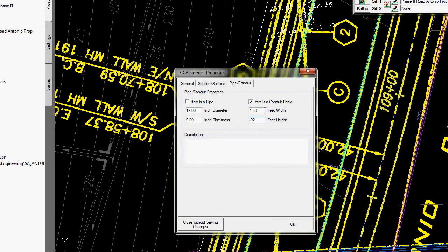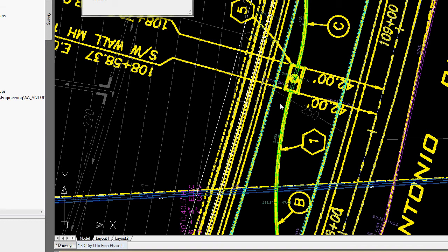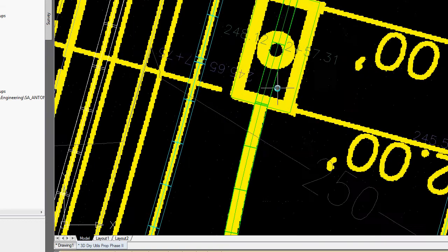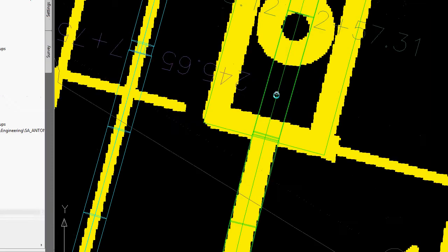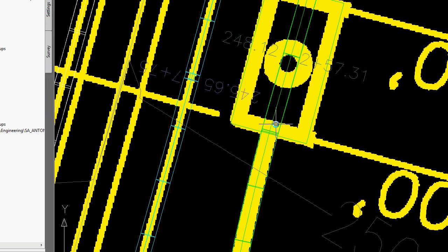Okay, and it sweeps a rectangle along this, and it makes that previous backbone line that I had the top of the conduit, because that's usually how we do dry utils, with a cover criteria. Water lines and everything else is its invert, storm drain and so on, but dry utilities, it does it from the top.